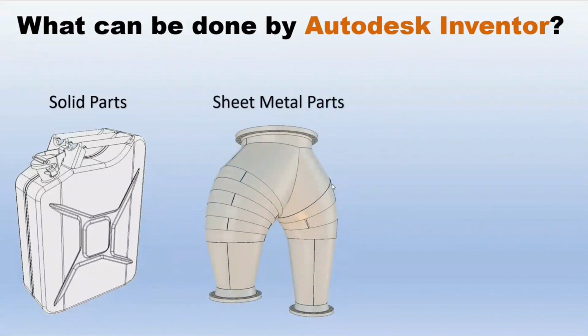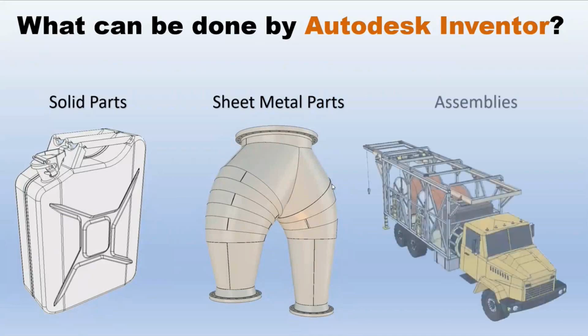You can make sheet metal parts. Around us and in our industry, a lot of things are created from sheet metal. In our industry, for example, the body of the storage tanks, the pressure vessels, towers, the heat exchangers, saddles, skirts, all of that is created from sheet metal. So easily by using those sheet metal features, you can make a blade development, and easily you can send that at scale 1:1 to your workshop drawing to prepare the cutting sheet for the sheet plate items.